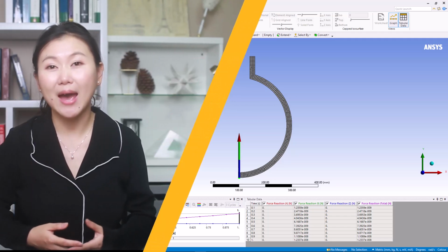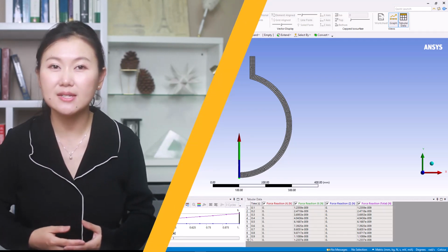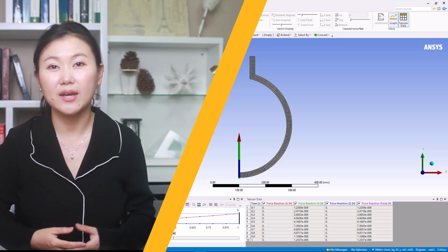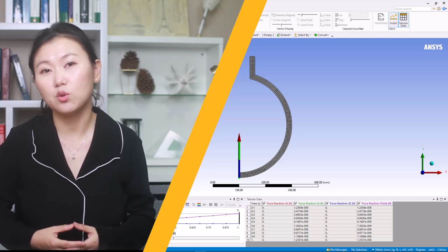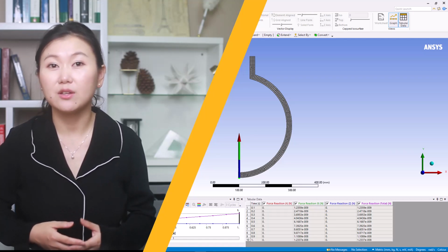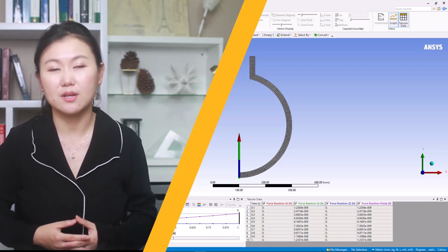Note that if we have non-zero reaction forces, they're reported on a full 360-degree basis. So you can interpret such output normally, as would be done with a 3D model. This is also true if we were to apply forces on the structure. We apply the total force and do not have to divide by radians or the circumference, for example.